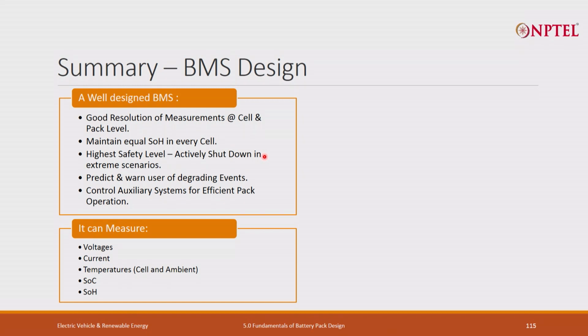It should measure voltage, current, and temperature, and calculate SOC and SOH. These are all fundamental parameters. Wherever there is a possibility, in the case of an HV high voltage pack, isolation monitoring. If you wanted to make a very heavy-duty and more reliable pack, pressure, vibration, and so on; all depends upon the cost and the functionality.